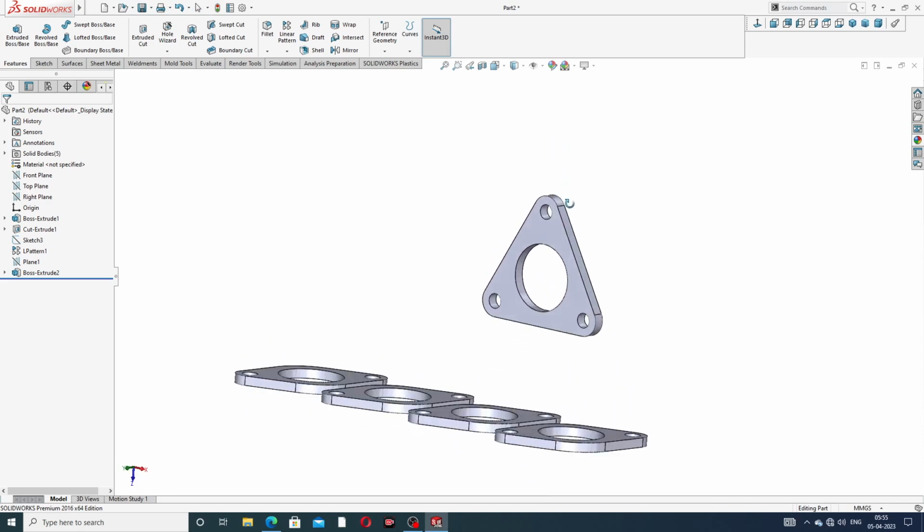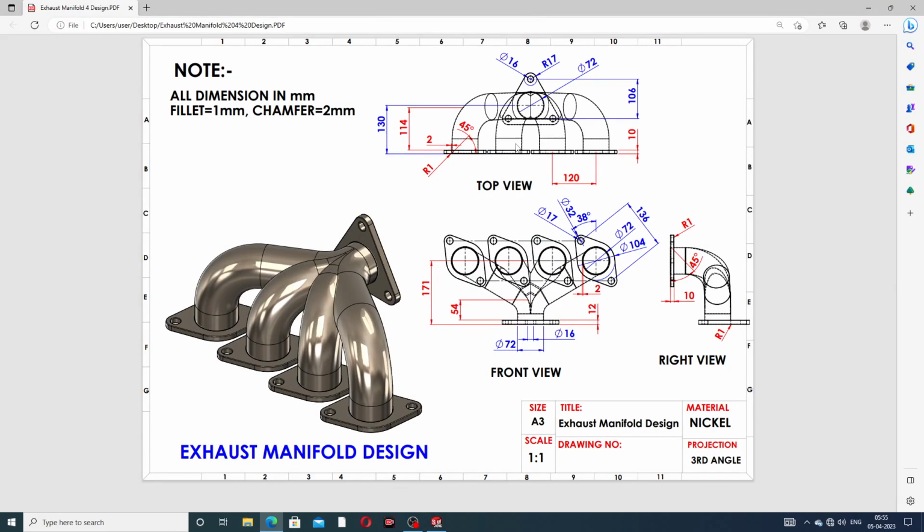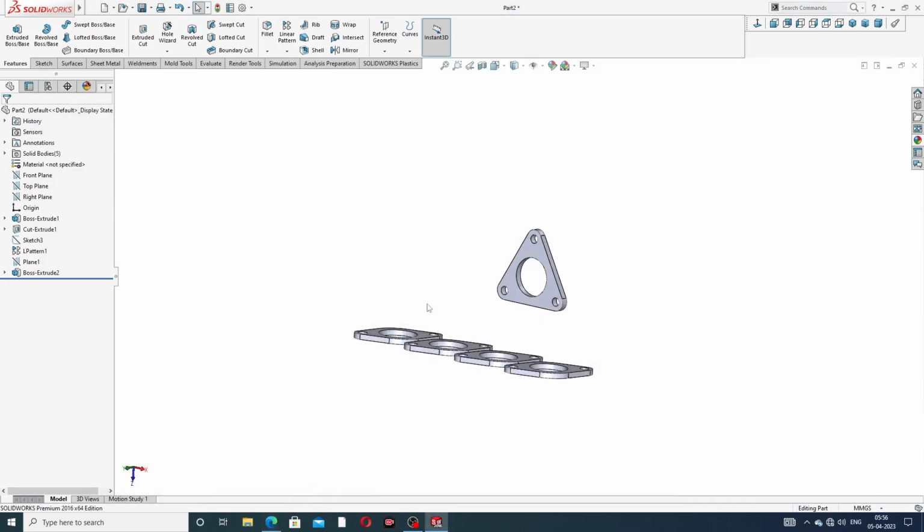And next is use a 3D line. Okay, all is perfect, and drawing this connecting to the pipe, and the pipe distance, this length is 54 millimeter and this is 114 millimeter, and two distances are perfect, and one point is missing here. This uses the fillet command, and this pipe uses 98 millimeter and this is 56 millimeter. 68 millimeter is okay.